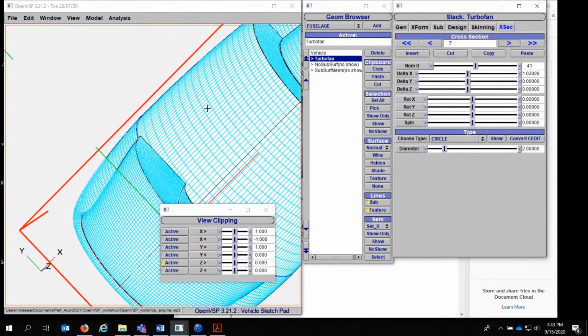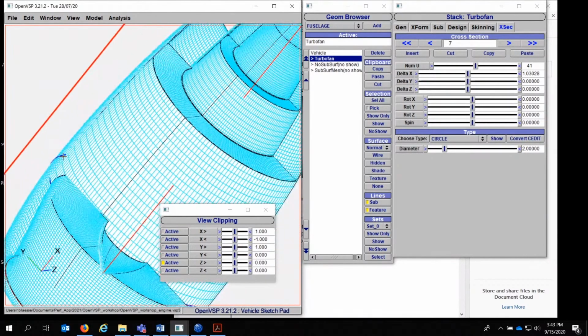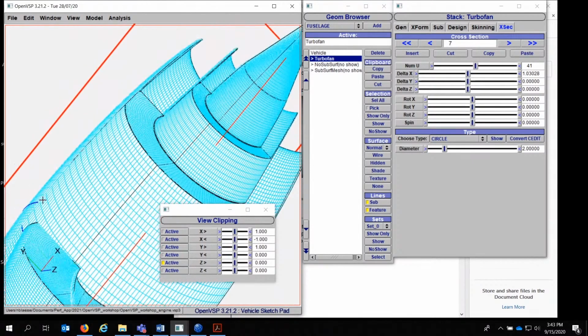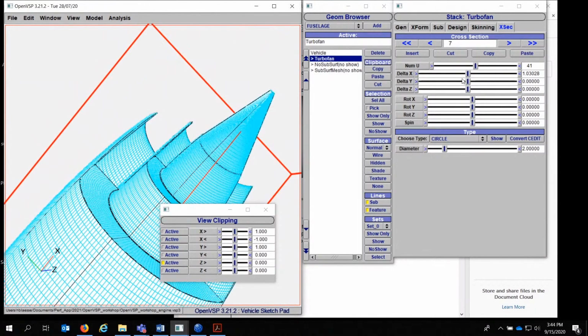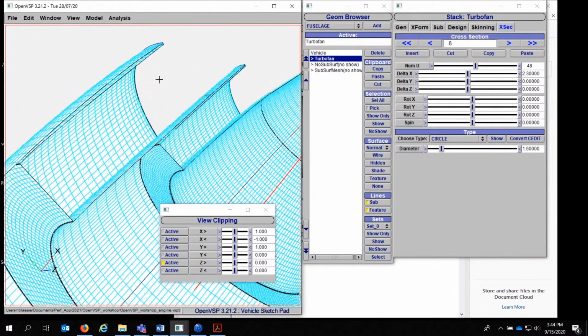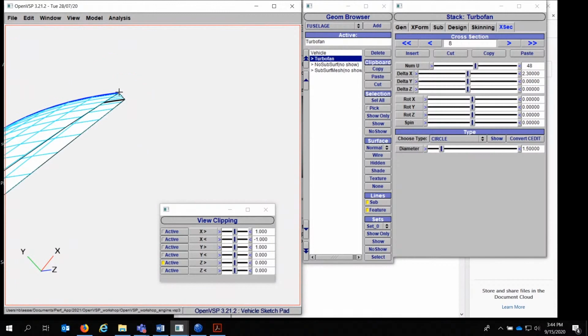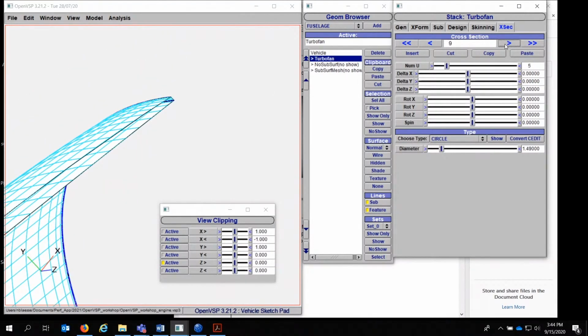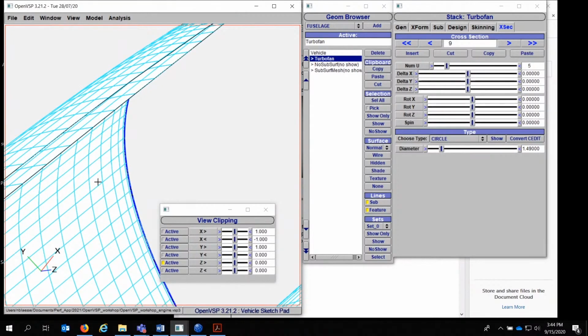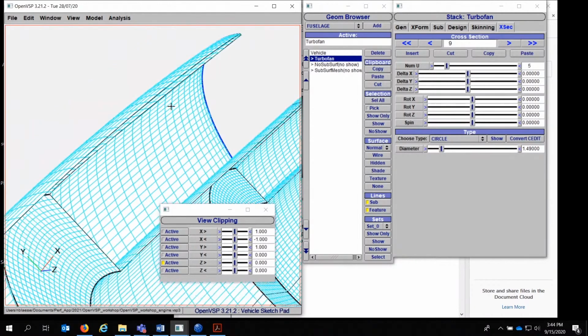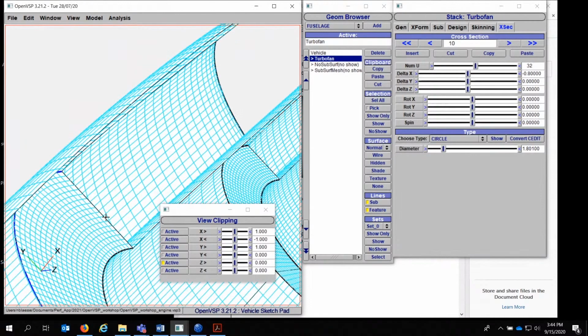Yeah, walking through. Next one is kind of the max diameter cross section right here. You could move this forward or aft, make it bigger or smaller to change the nacelle shape, or if you had some kind of optimizer, you could probably try and run that through. Let's see, go into the back. Here's my blunt trailing edge. It's just a very thin trailing edge on the back, and then it doubles back on itself right there. And I put another subsection here so that I can separate this inner surface from the outer surface for that thrust drag bookkeeping issue. And then I moved it here.